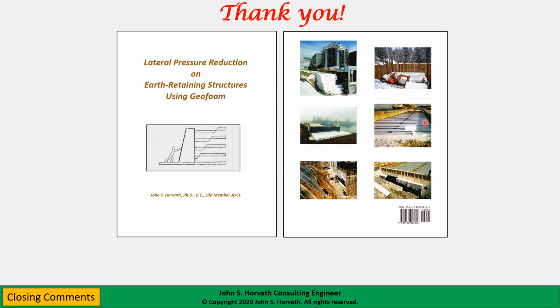If you've ever done analyses of anchored bulkheads, you know that under gravity loading, the toe kickout tends to be the most critical failure mechanism, whereas under seismic loading, both analyses as well as experience indicate that tie rod failure tends to be the critical failure mode. So this was a seismic enhancement of this wharf, this marine facility, obviously, to reduce the stresses around the tie rod level and increase the seismic stability.